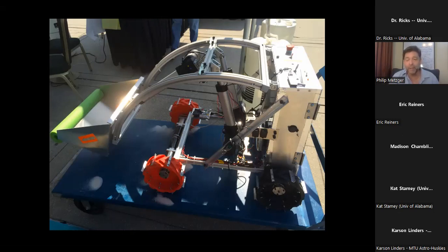And as that wheel turns, it's going to shear the soil, but one wheel turning, you haven't increased the torque enough to get forward motion. And so the vehicle is not moving forward. It's simply one wheel turning in place. And that one wheel turning shears the soil, loosens the soil under the wheel. And as a result, you end up with a hole under the wheel.